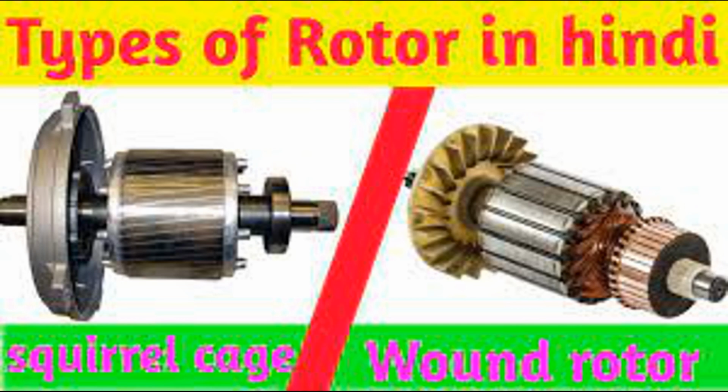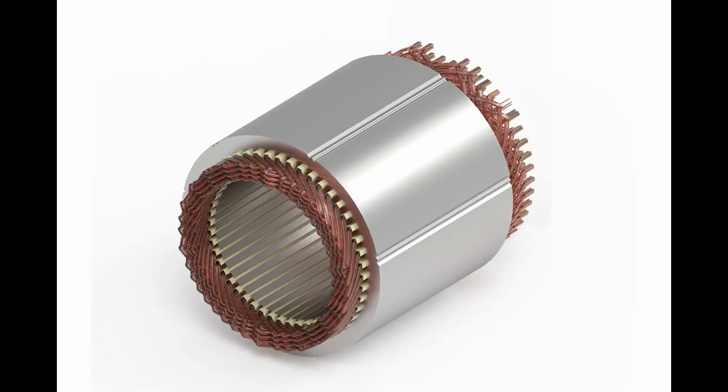To achieve smoother DC, a filter, often consisting of capacitors and sometimes inductors, is connected to the output of the rectifier. The filter helps smooth out the waveform by storing and releasing electrical energy, reducing the amplitude of the ripples. Voltage ripple. The quality of rectification affects the amount of voltage ripple in the DC output. Higher quality rectification and filtering result in lower voltage ripple, which is important for providing stable power to sensitive electronic devices.